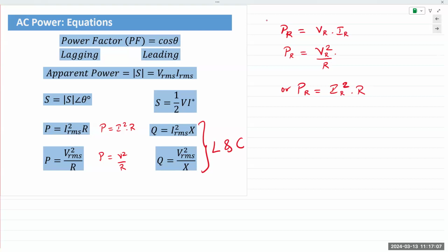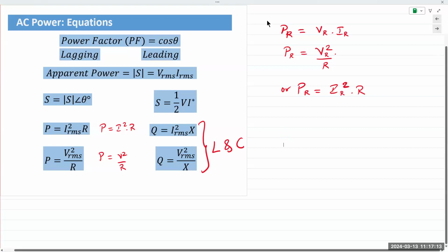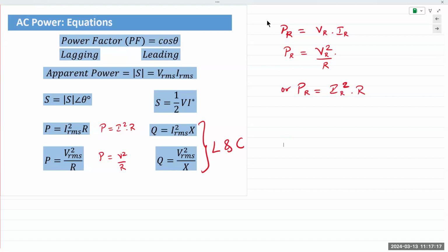One thing to keep in mind is that the reactance for an inductor, and hence the impedance for an inductor, XL, ZL, and then the reactive power for an inductor, which is QL, are all positive. Right? That vector is pointing straight up. XL, ZL, and QL are all represented with a plus sign. They're all considered positive.